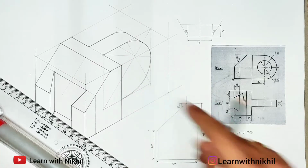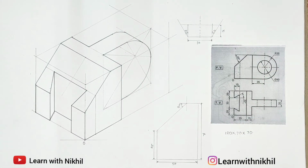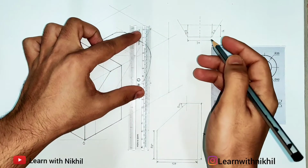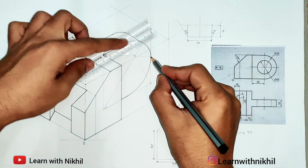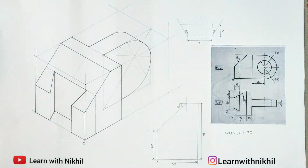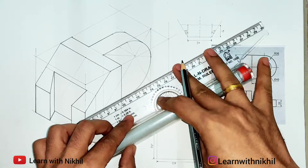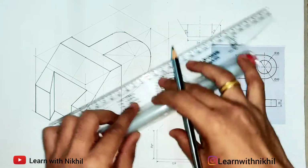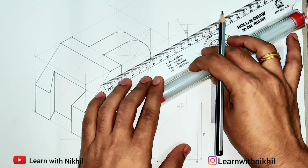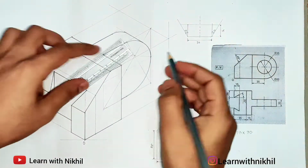Now inner, again we have a circle, the same procedure. The diameter given is 40 millimeter. Now first we will locate the center point, and from the center point 20 millimeters on each side we will find, as it is totally drilled at the center. So first I locate the center, 35 millimeter. I'm drawing a light line. This is 70, so marking the center point. So this is the entire center point.